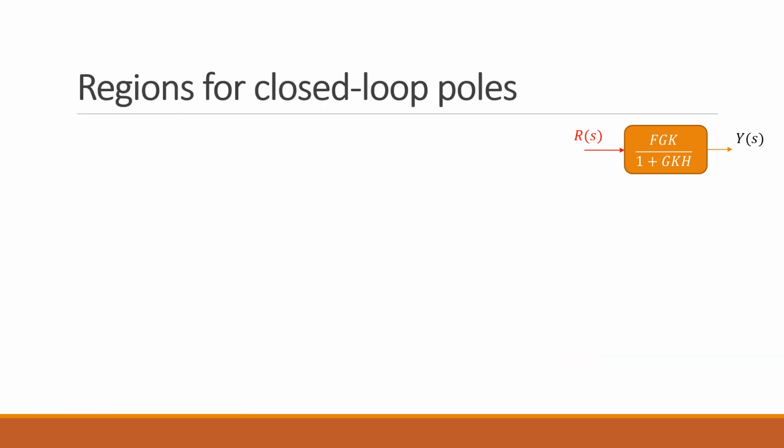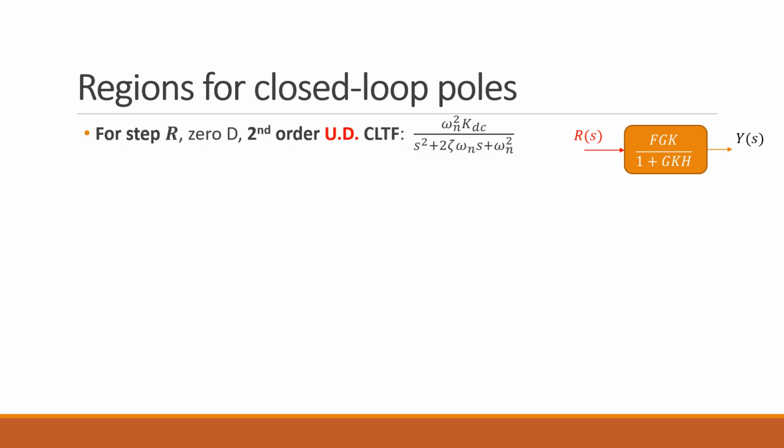Let's relate back all these formulae for settling time and overshoot to the specifications. We're going to take a sample case where the closed loop transfer function is an underdamped second order system, because we just have the formula for it. Let's say one of your specifications is that the output Y(s) has settling time less than 2 seconds, which means the response y should reach within 2% of the steady state value in less than 2 seconds.